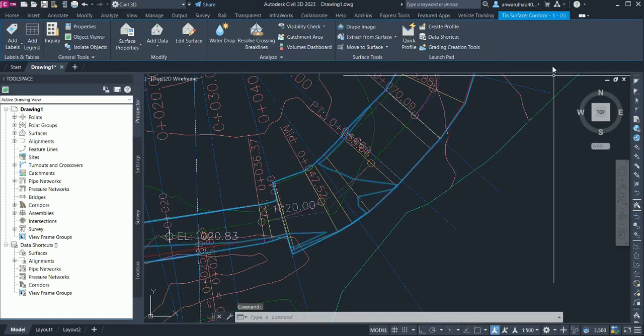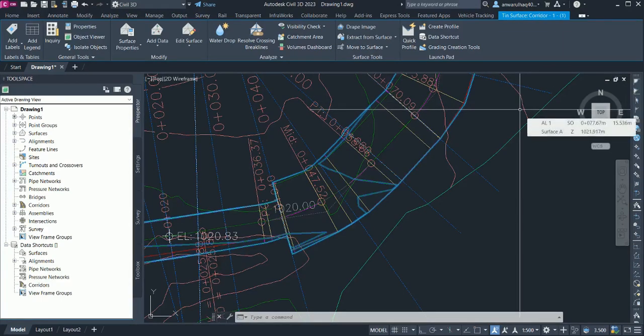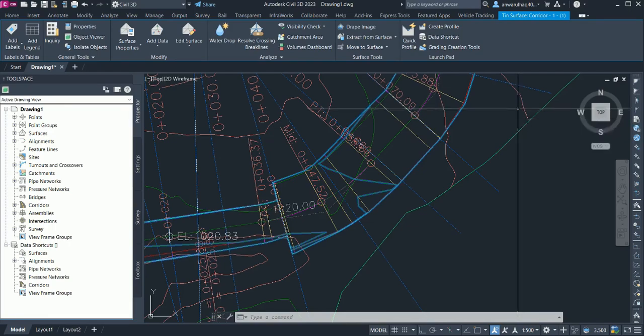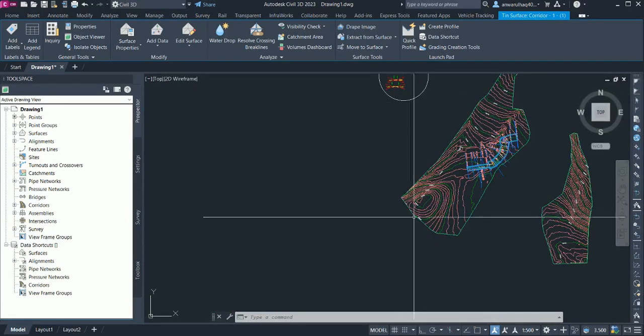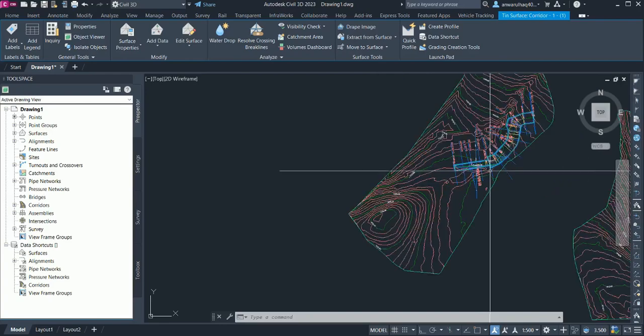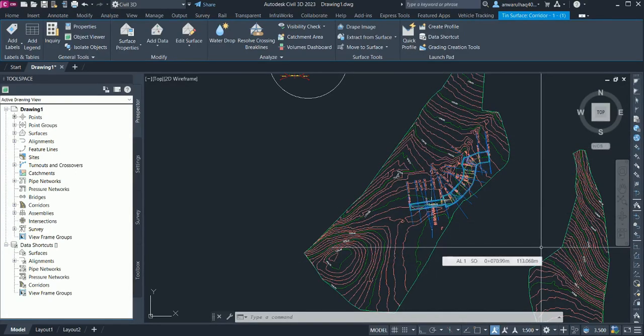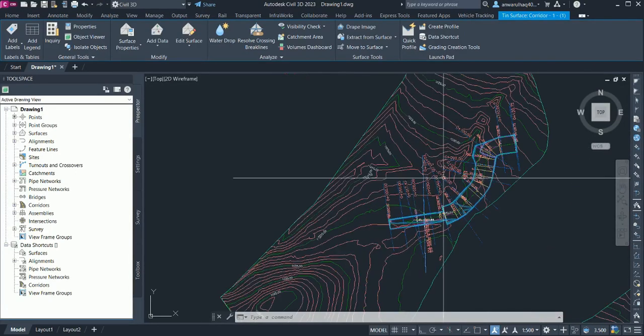For example, if I select here, this is our corridor surface. In the tutorials we have already learned how we created these surfaces and how we integrate them. After all, our surveyed side and our requisite side will be accumulated and integrated with all these features, and you can find a new surface called the as-built surface.